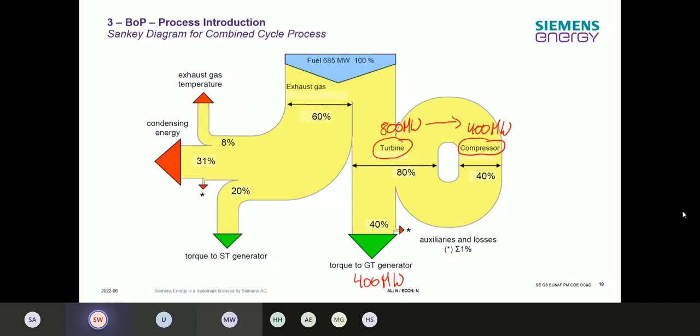from the turbine, what the turbine is producing, is getting into the compressor, and the other half is what we really see on the generator. So that's what this should tell us. So the turbine itself is normally producing double the power you're seeing on the generator outlet, because you need a really massive amount of power to run the compressor. And that's what is shown in here.